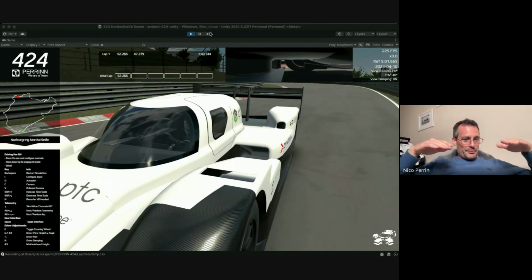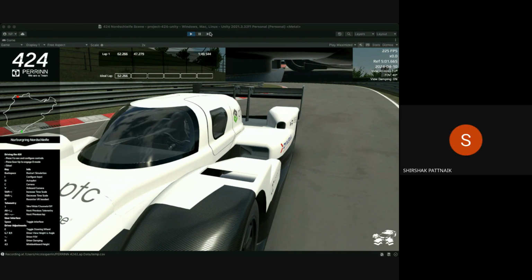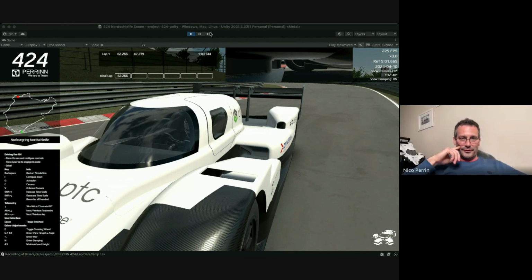So when you go over bumps, if you are the flap, what controls you, there's no inertia about it. You're still very much controlled by the aerodynamic load, the hinge, and the force from the spring. I hope you see what I mean. It only really moves when the aerodynamic load is changing with velocity. There will be a little bit of movement on bumps, yes, but it will be very small. Okay, all right, thanks for your question.